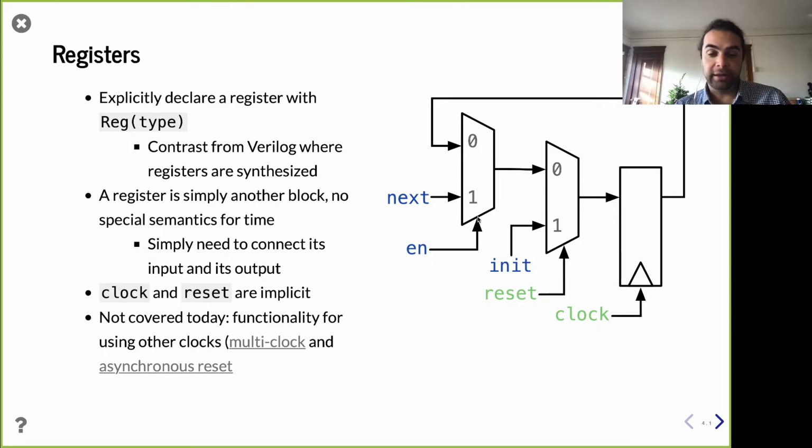If the write enable is off, we're going to take the old value. We're not going to change values. That's the 0 in here, selecting the mux, taking the old value. Going a step further, do I want to reset to a known value? If so, if reset is 1, it doesn't matter what was in the register before, or what the input had. I'm going to set this initial value. And then perhaps reset is 0, in which case we'll have a chance for this to come through.